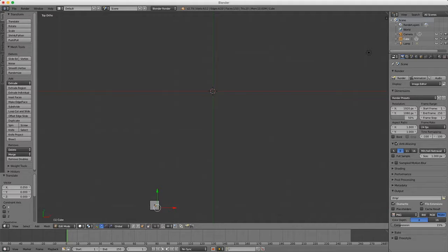To deselect the bottom face, press A, then press A again to select the entire leg. Press Shift, C, to ensure the 3D cursor is at the grid center. Remember, to pan the view, hold Shift and the middle mouse button. To zoom in or out, use the scroll wheel. Navigate to the pivot point menu at the bottom of the viewport, and select 3D cursor, to change the pivot point from median point to 3D cursor.